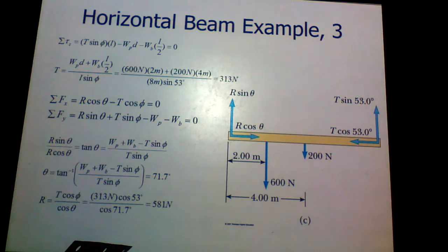Okay, so we can solve for tension first, because ultimately we want to solve for tension. I know that torque on this particular beam, sorry, not a ladder, beam, is equal to the force times the radius, force times the lever arm. The force R from the wall isn't going to apply torque, because my R would be 0.